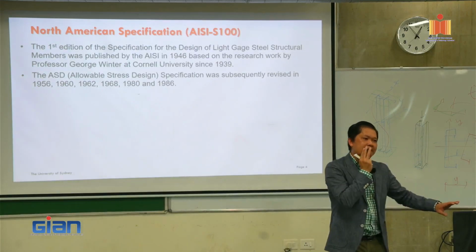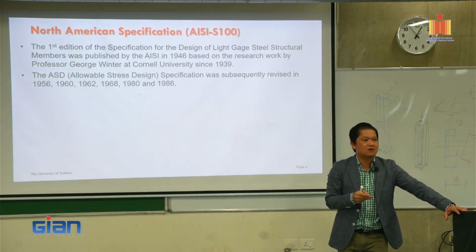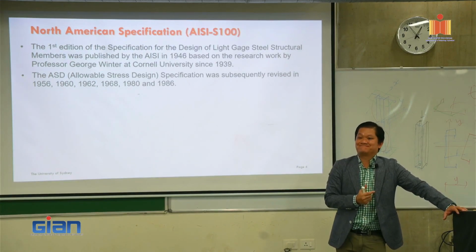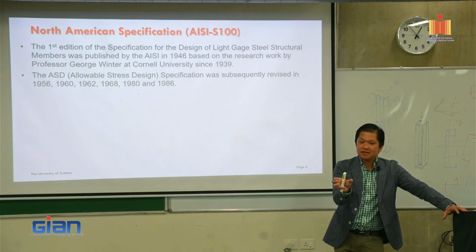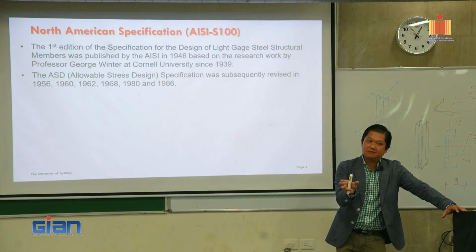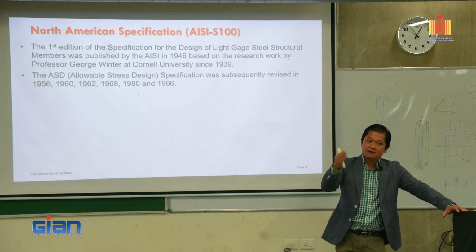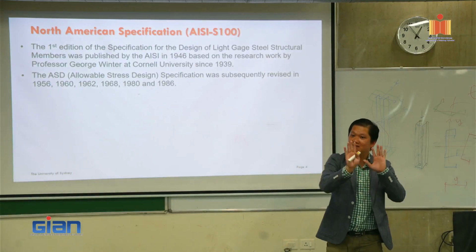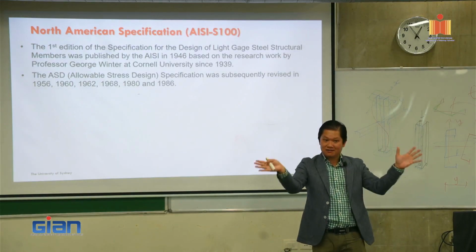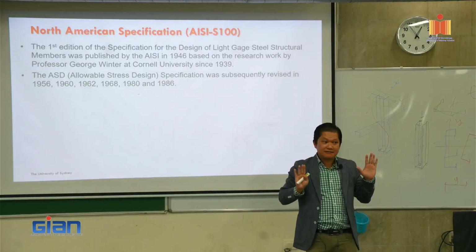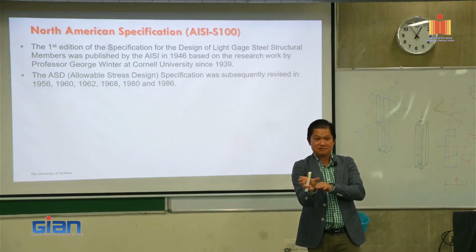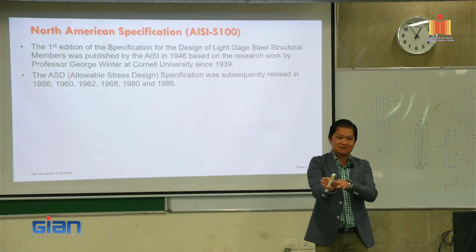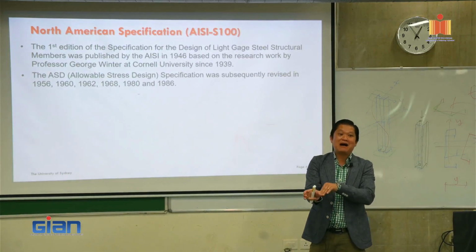We have a couple of papers on storage racks, with the C section. In practice, sometimes they don't make the wall. They just attach something on it to make the covering, and when it is subjected to wind from two directions, that upright or column will be subject to biaxial bending.